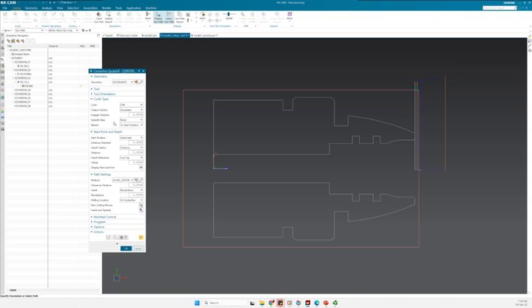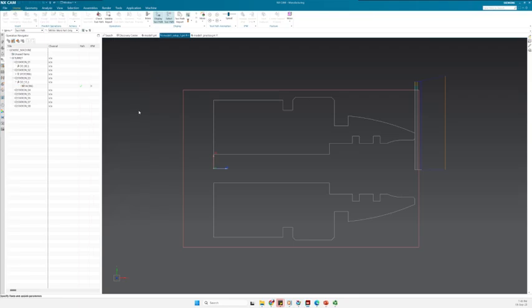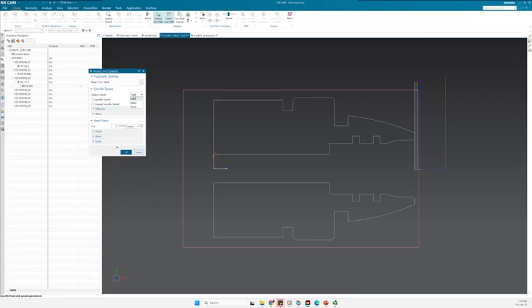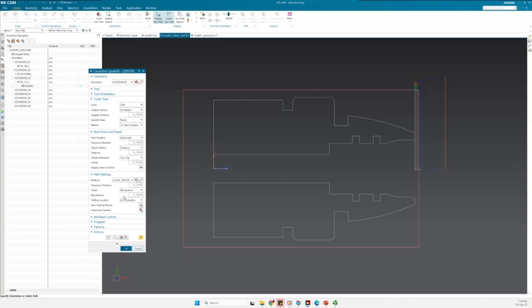So you know that the spot drill should be of very high spindle speed. So for example, I go to here again, spindle speed, selected spindle speed per RPM. For example, I can put, I don't know, let's say 900, for example, or 1000, and this is fine.